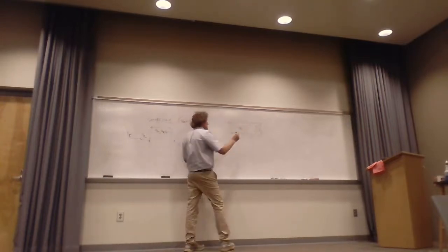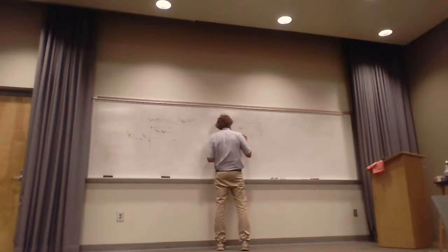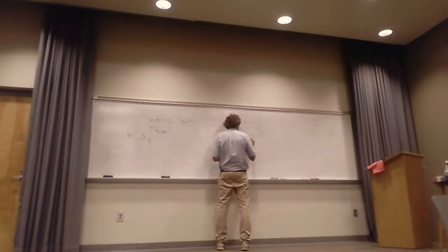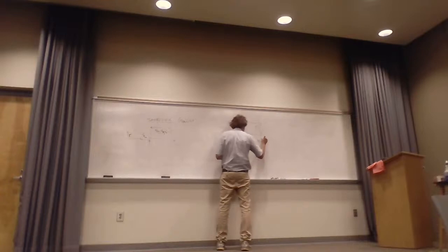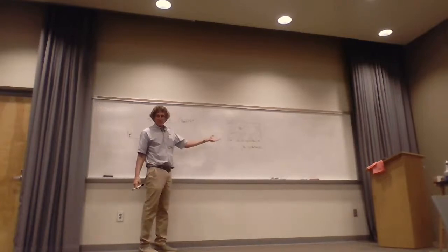You found out one thing. If this is length L, you said that Zin was equal to Z0, the characteristic impedance, times (ZL plus j Z0 tangent of beta L, if it was lossless) over (Z0 plus j ZL tangent of beta L). Do you remember that? All right, that's for a lossless region.